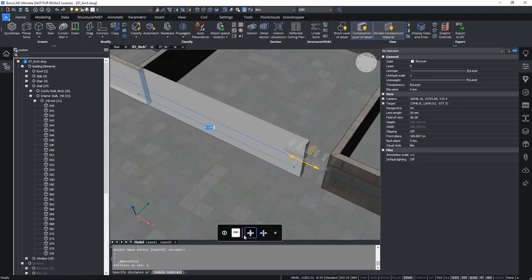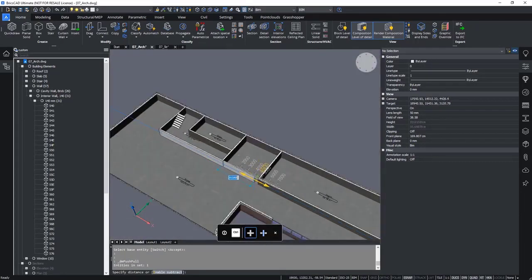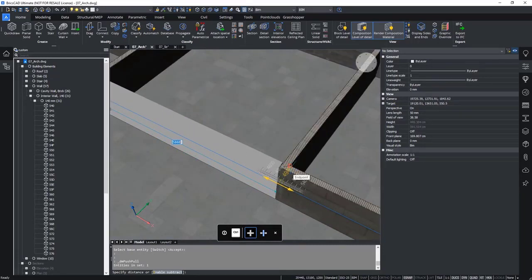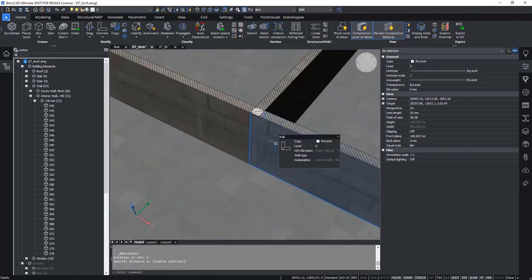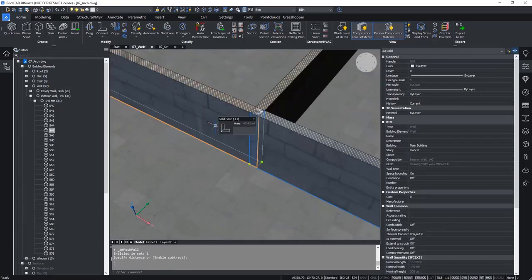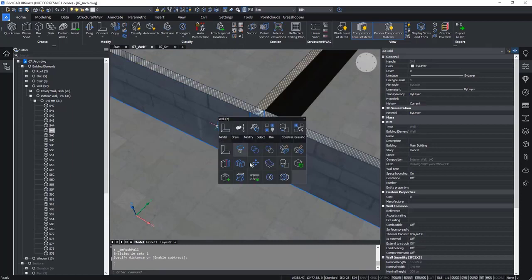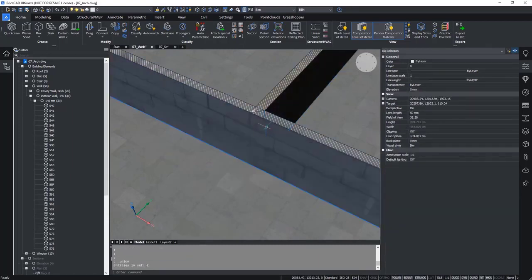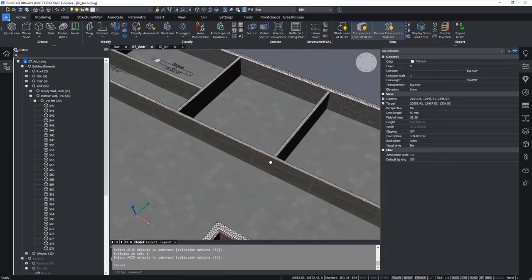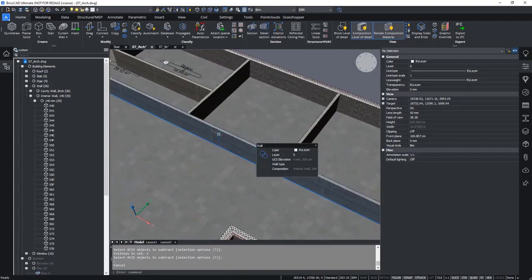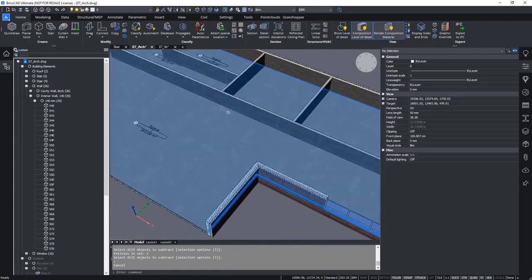Make sure that here it's really disabled, the subtraction option, otherwise you will be subtracting from your solid face. And then you extrude all the way until it's in the other wall, and then you can union still to clean it up. And maybe subtract here if needed. Okay. And then the end result should look like this.